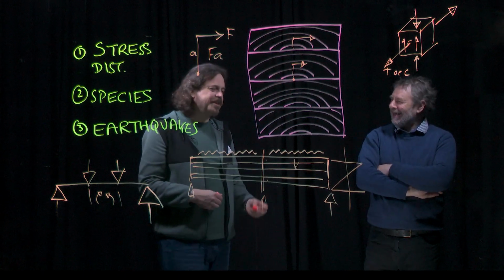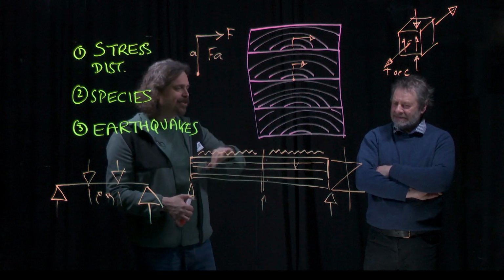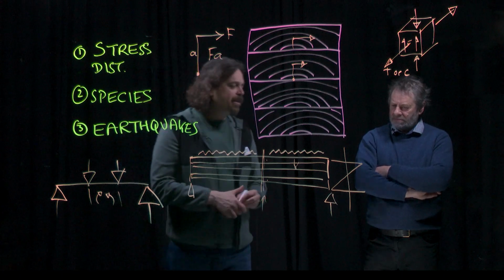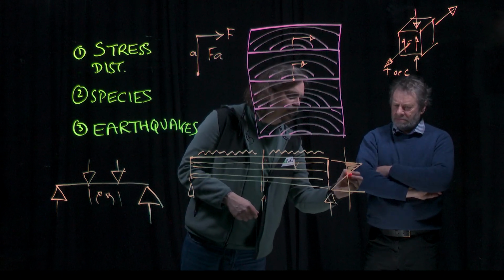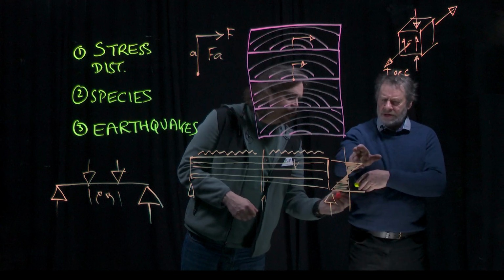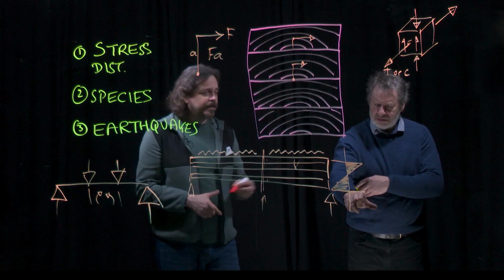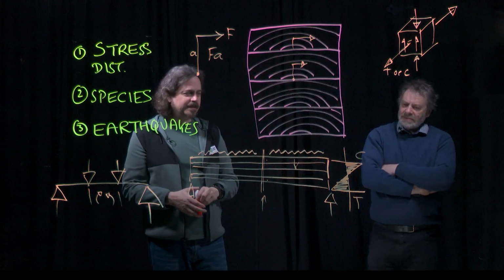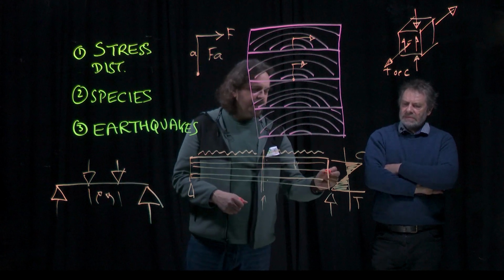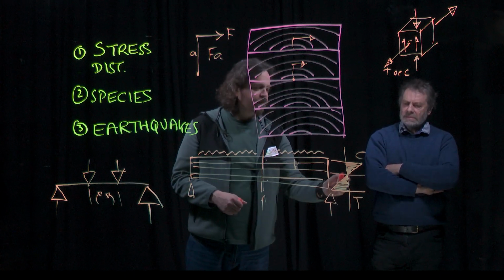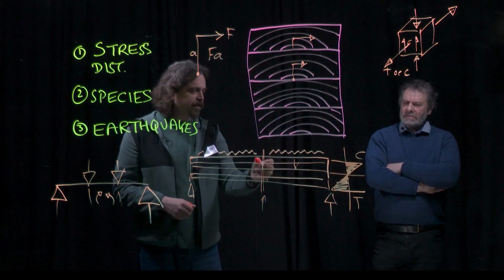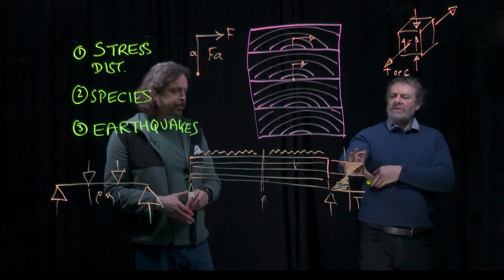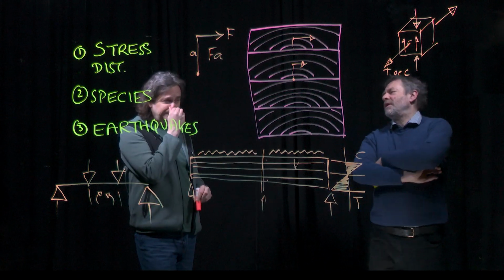There's a sign convention. Strictly speaking, you should decide which side is compression and which is tension, and I've forgotten what convention I've been using. But basically, you end up with a triangular system. So here we have tension, and here we have compression. Sorry, yes, compression. I mix it up as well. So we've got zero axial force in the middle, compression on the top side of this bending beam, and tension on the bottom. And this would be considered to be an idealised diagram.